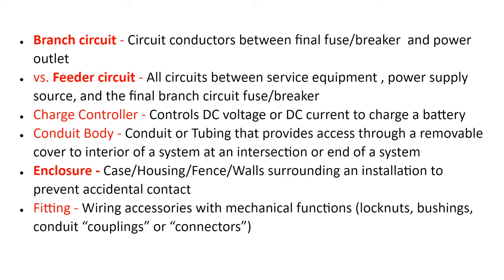So the front part of National Electric Code has a lot of terms and conditions. I've highlighted some things that, enclosure is a fence, a housing to surround and protect from accidental contact. There's a difference between fully enclosed and enclosed. A complete tube might be a full enclosure, whereas a wireway, like a wire mesh, depending on how thick that mesh is, might not be considered fully enclosed.